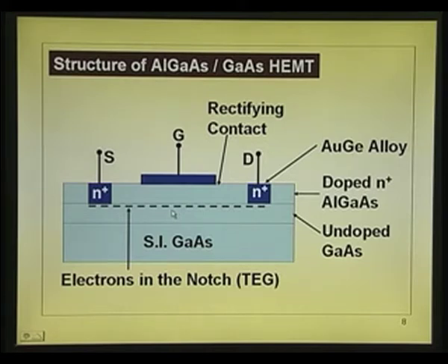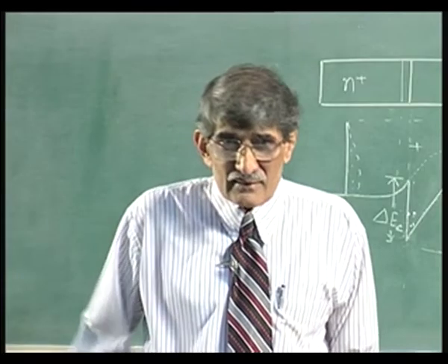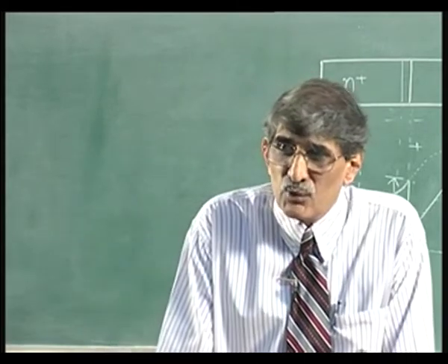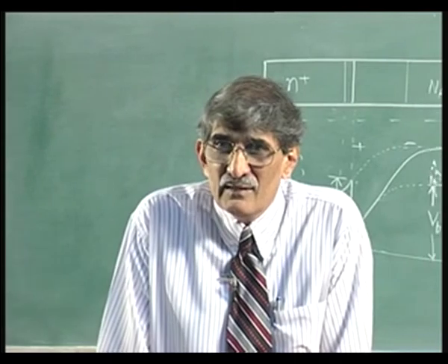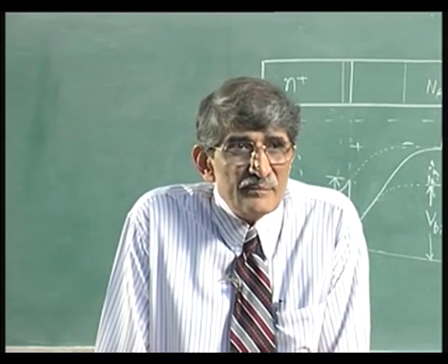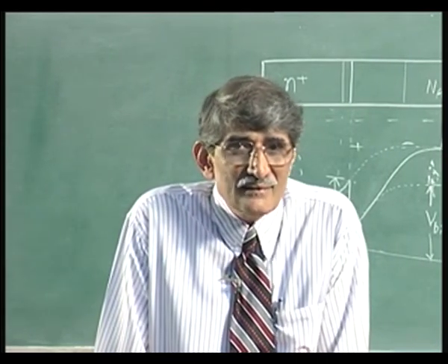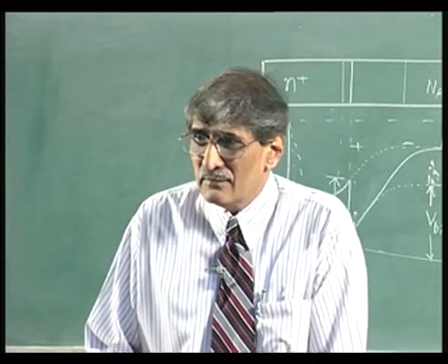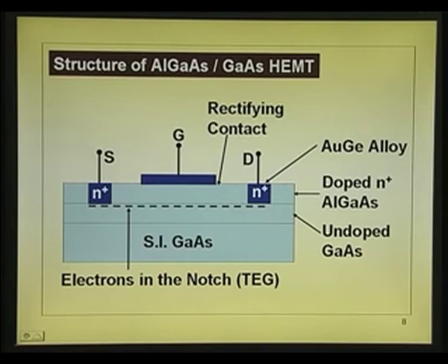In the case of MOSFET, once it is inverted, you apply voltage between the gate and the source, and the charge in the inversion layer gets affected. For example, above the threshold voltage, if you apply VGS, that VGS minus V threshold appears across the oxide, and that changes the charge. Similar thing will happen here. I am not discussing it right now, because I am just giving you the principle. We will go into more analysis after discussing a few aspects.